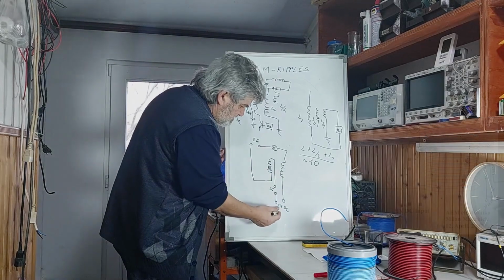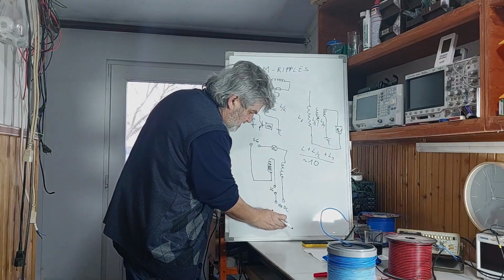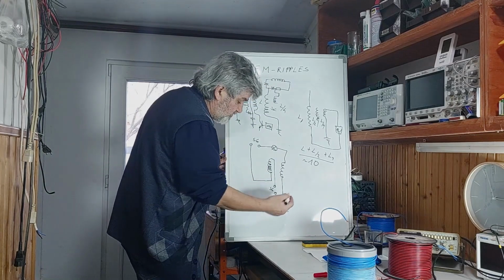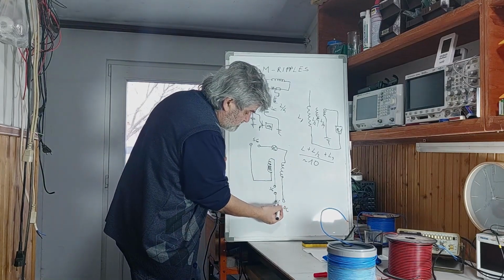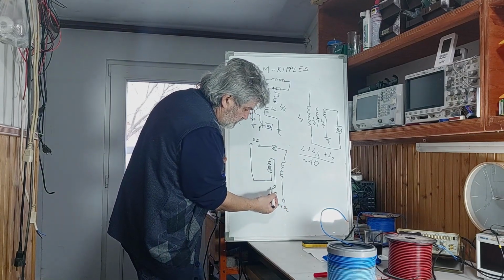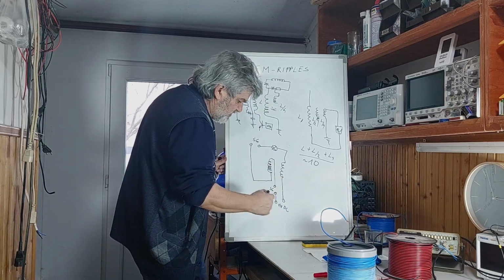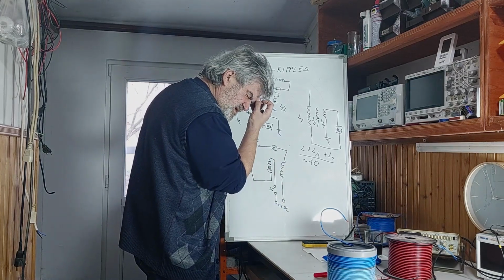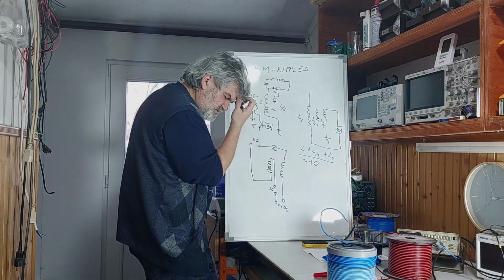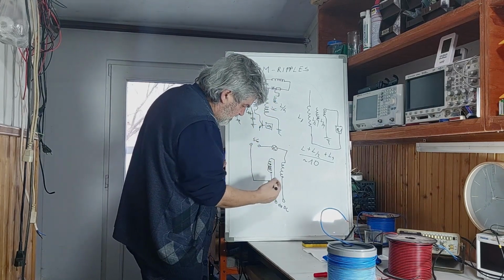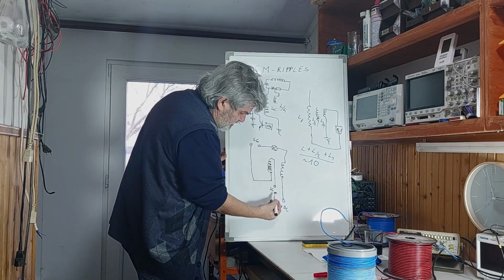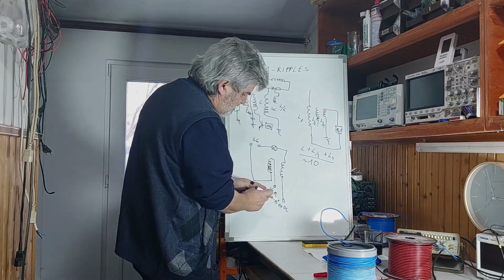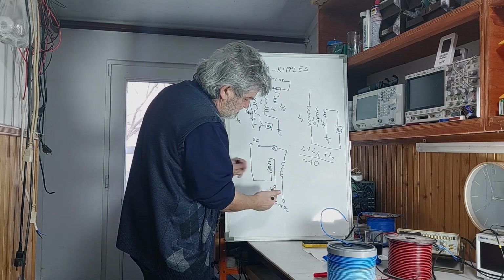So this is an electrostatic machine, but it could be an extremely high voltage transformer. It is the source. It is per gap between 300,000 or 500,000 volts. It is about 5 to 7 centimeters per gap distance.